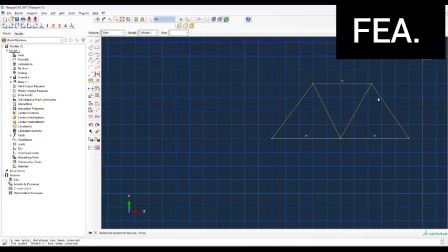Okay. So now we have the general skeleton of our truss system. What we can do is prescribe dimensions. Using this one right here, I can prescribe some length to my truss system or different elements. And I can also prescribe constraints. So I click this, and I get the constraint tab. We can do a horizontal one on these, obviously, because they're going to be straight. And then this one right here.